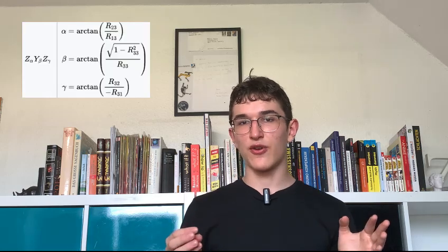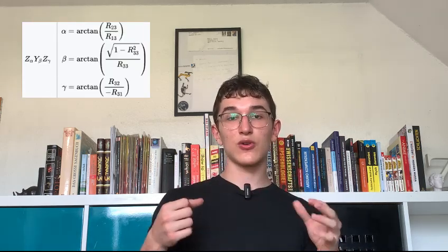So you take all these 4 values, you do some funky math, put them in a transformation matrix, do that for every joint. And if you want to do forward kinematics, if you have 5 joints, you take the transformation matrix of each and every joint, you multiply them, then you do some, I think Euler had a few formulas to extract the coordinates, and then you have your coordinates for forward kinematics.